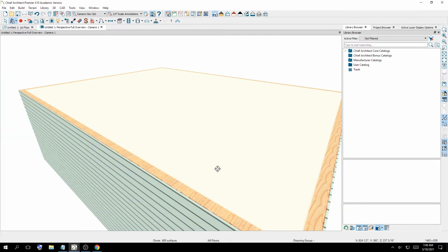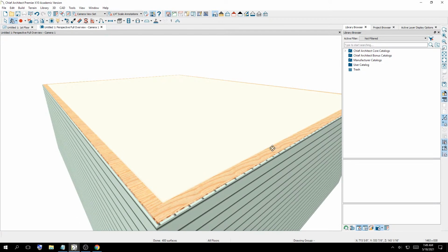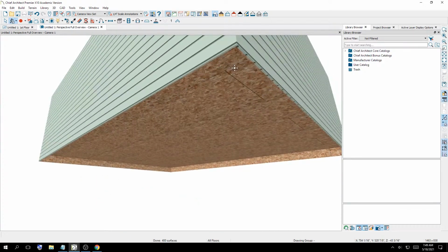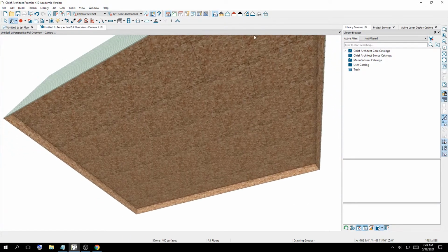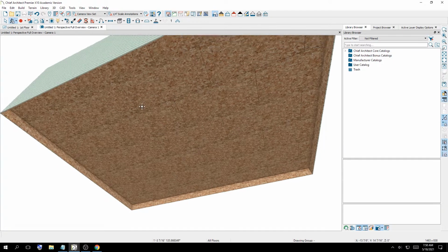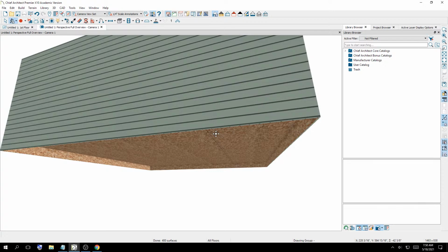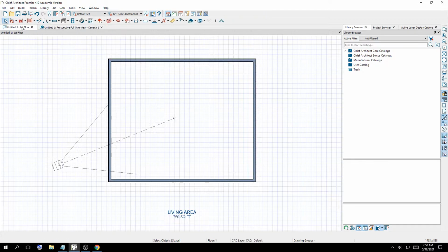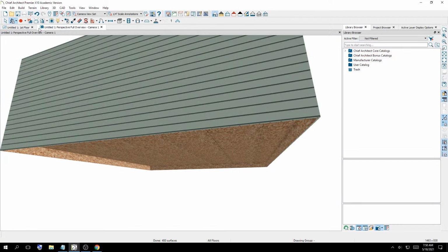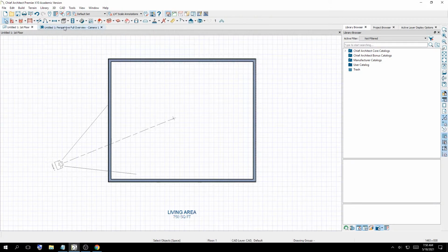If we zoom in, you can see that this is, let's say, the header plate of our frame. You could consider that there's a sill plate under here. You can see that there's OSB, in a tiled, brick-like pattern, the way that you would put down a subfloor. You can see that there's a hollow section under here because there are no joists. Obviously, there would need to be floor joists here for this to be structurally accurate, and we have not built those yet. If you remember when I was going over those tools, if I were to switch the tab, you can see the tools themselves right here, I could auto-generate floor joists. You can see that there's multiple tabs here when I bounce back and forth.